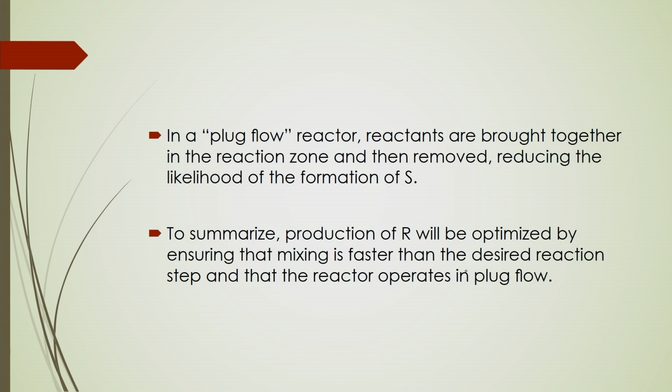Now, in a plug flow reactor, reactants are brought together in the reaction zone and then removed, reducing the likelihood of the formation of S. So, if you are using stirred tank reactors, you get those mixing characteristics, that is, arbitrary directions of the fluid element, whatever substrate or reactants you are using. In that case back mixing may happen. Due to that back mixing, the yield of the reaction will be low, whereas in plug flow there will be no chance of back mixing of the reactant. So, it is called plug flow phenomena.